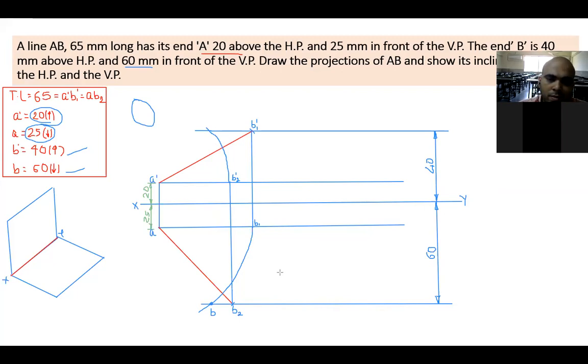Yes, Mayank, go on with the question. Sir, can you repeat what to do after B1 B2? Okay, take A B1 in your rounder. And then from point A, rotate your curve till here. Wherever it cuts this line, that becomes your B. And the same procedure you have to do here. Take A dash B2 dash in your rounder, and make a cut by keeping A dash as the center. Wherever it makes a cut, that becomes your B dash. Is it fine? Yes, sir.